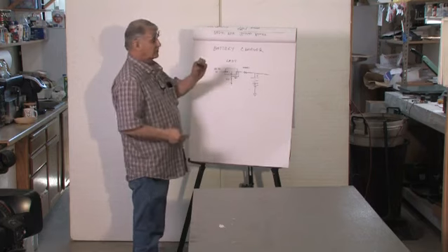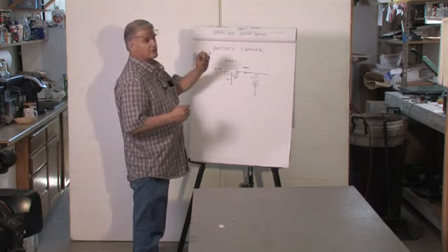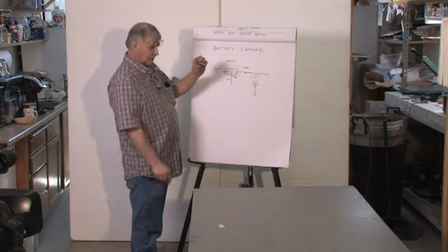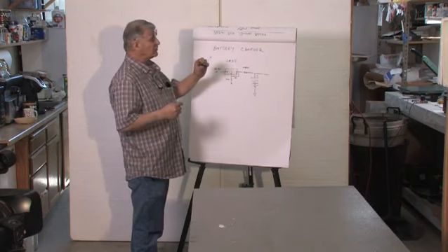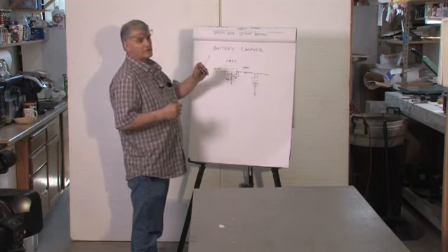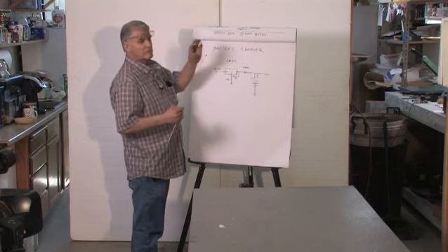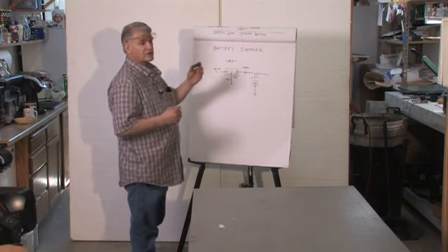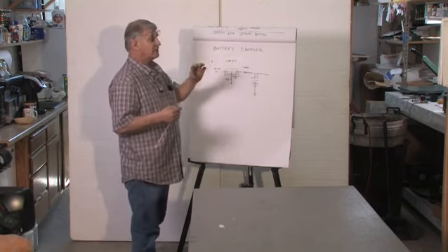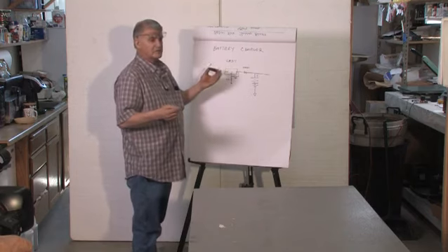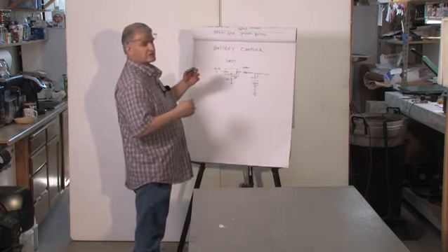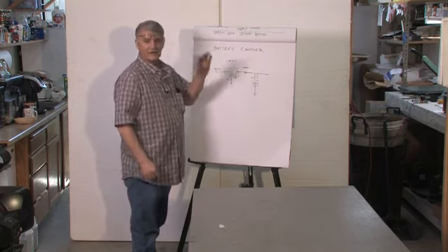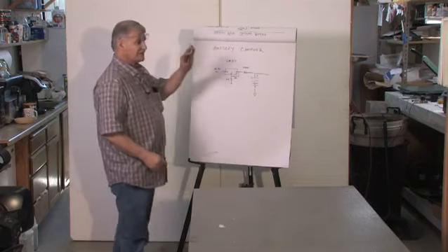You don't want to run these to 0. When you run this type of battery right down to 0, you run the risk that the cell will not operate after that. Now, the reason that you don't really run it to 0 in a solar light is because the LED is at 2.8 volts. So the minute there isn't enough voltage to run the LED, you're not drawing anything from the battery. Okay. So that's the little trick there.